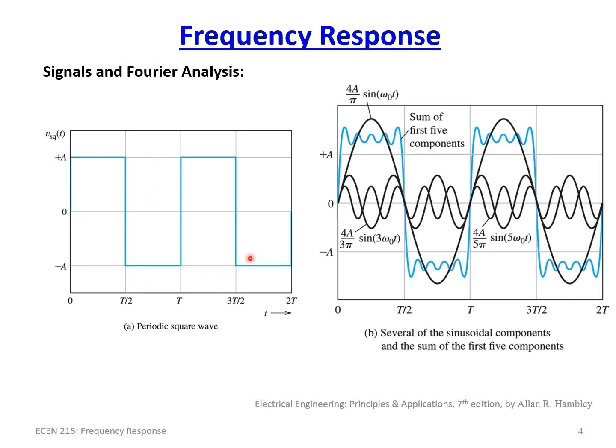Again, you can represent that signal as an infinite sum of sinusoids. And it takes a lot of sinusoids to create a square wave, but you can do it. You have the base frequency here. This will be at 1 over T for the frequency. So you have the base harmonic sinusoid here. But obviously that one by itself just creates a sinusoid.